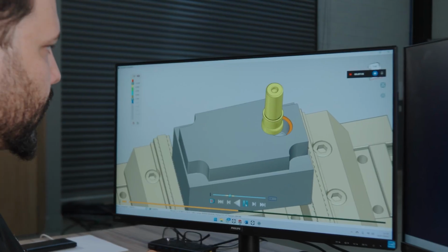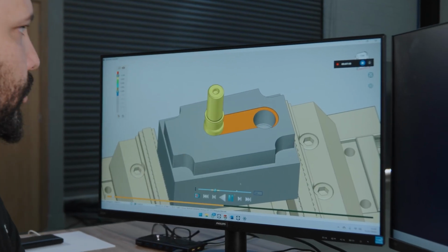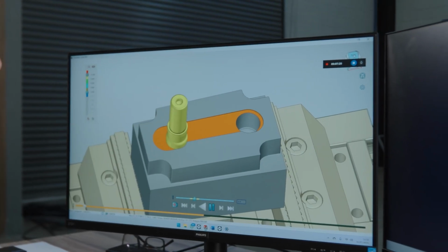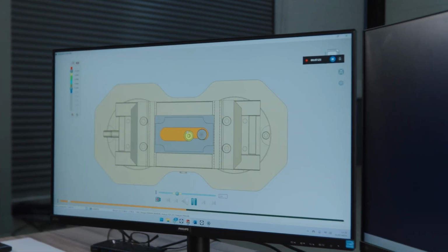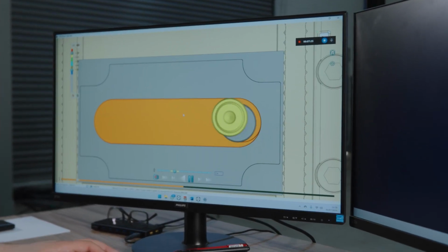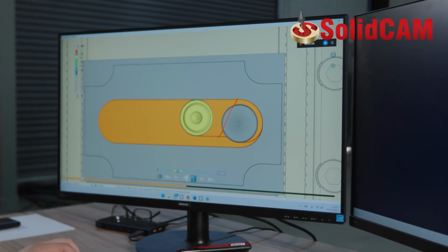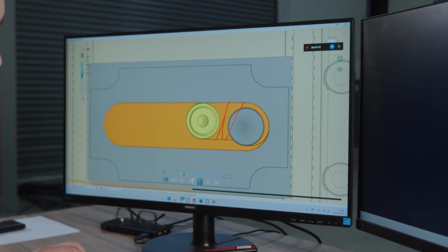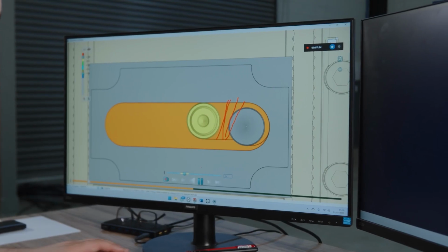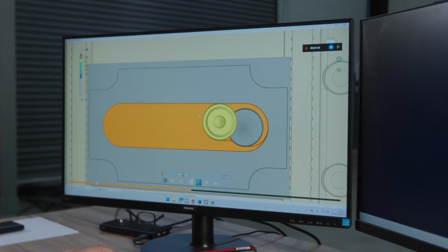Do you think that's all? It's not over yet. There's a keyway process on this part, and you'll see that you make keyways several times a month and never paid attention to this problem. Come with me. Here I have a traditional keyway machining process for cutting keyway slots. And now look at what happens in this situation. While the cutting tool passes through this particular point, it removes its entire full diameter of material when it is moving in this direction.